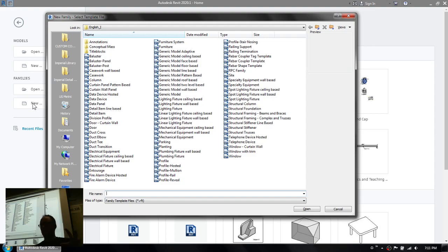You can copy the geometry from your existing family into a blank template. Now there might be a few dimensions that don't come across, but you can copy that geometry over. You might have to do some reassociation with the constraints, and we're going to be talking about constraints over the next couple of weeks. But it is definitely possible.